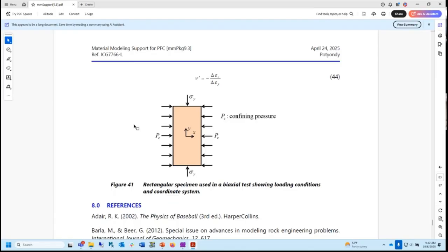And so if you do a two-dimensional problem in theory of elasticity, you have to specify what's going on in the third dimension. And so any computational scheme in a continuum mechanics world, as soon as you run a 2D code, you always have to check a box: I'm running a 2D problem under plane strain or under plane stress. Of course, you could have other weird variants, but in almost all cases, you only consider plane strain and plane stress. So that's proper theory of elasticity.